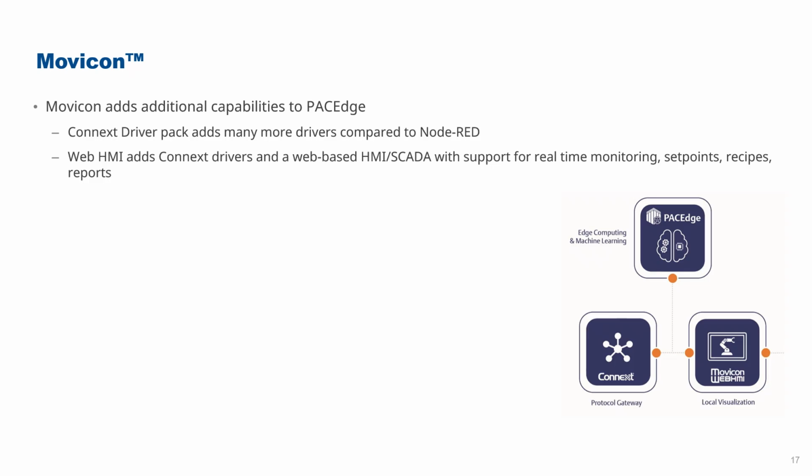So you might find that Connext can make it considerably easier to develop some functions compared to developing a flow in Node-RED. So for example, with that machine-to-machine capability, what Connext can do there is you can configure an I/O tag that's associated with 2 different PLC drivers and 2 different PLC devices. So they can even be different types of PLC. So for example, you could connect an Emerson PLC to a third-party PLC.